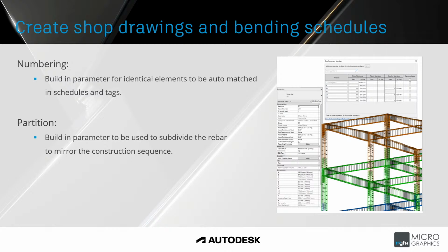The numbering, if you place a certain shape once and you give it a number, call it say bar 1, then if you place in another column the same shape with the same size, it will automatically recognize that number and also have it say bar 1, so similar sized rebar objects will have the same numbering, and that is auto matched.